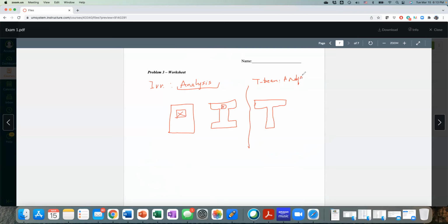And now for the T-beam, be careful, if I show you the T-beam, I may ask you to pick out the effective section. From the homework, you have done that, meaning I will give you a drawing like this and ask you to determine the BEFF, the effective width, that is BE right here, equal to BW, which is the web width, plus 2 times the wing width, BF. I will probably ask you to do that, and you use this number for your section and do your analysis.